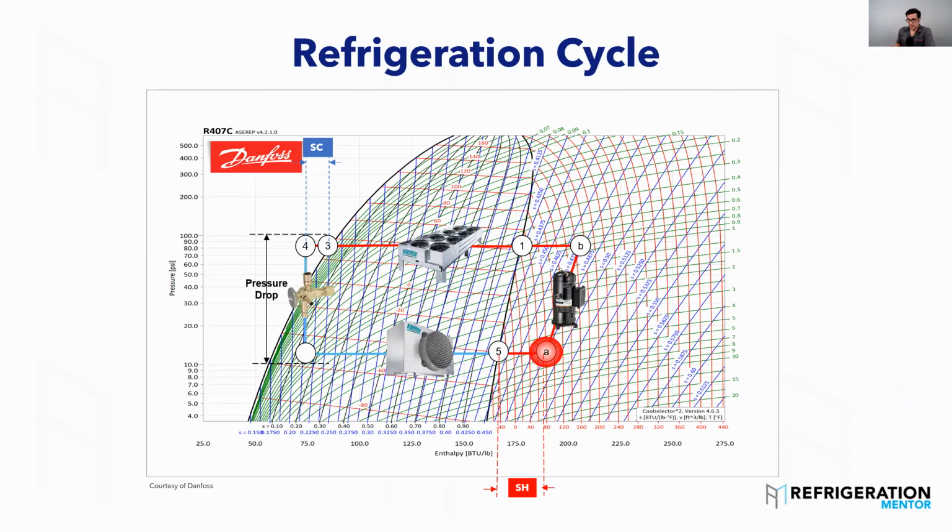So that's how the enthalpy diagram works. You see a lot of these red and green lines. They all mean something. Engineers use that all the time, but the main ones you're going to use is this red line. And you notice this is 407C. Do you see how this red line I have is straight, but the 407C line is on an angle? So here's your bubble point temperature, here's your dew point temperature. They're different. So it's good to know that stuff.